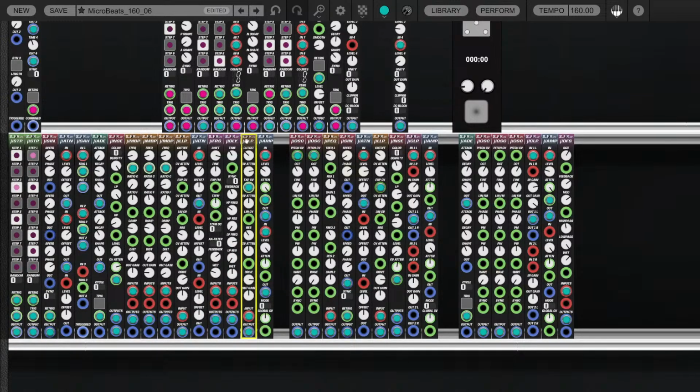So we've been discussing this filter that muffles the delay. And the delay also feeds back into another low pass filter that goes through an attenuator back into the frequency shifter. So we have a feedback path here that feeds back the delayed and already frequency shifted signal to the frequency shifter to be frequency shifted and delayed again. Just to create some interesting tones. We have to be careful though because of the resonances, and you kind of hear that it is ringing out every now and then. That's why we added the low pass filter.